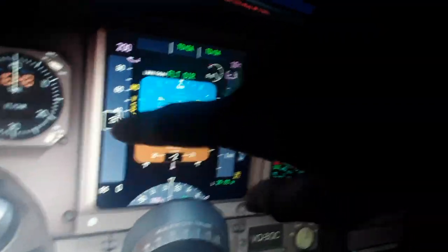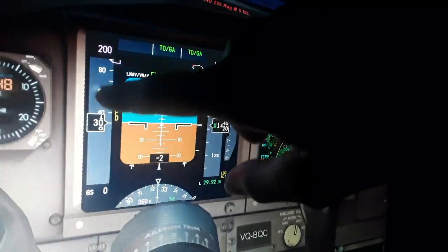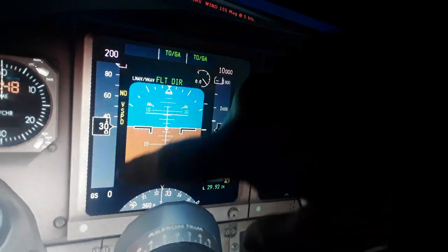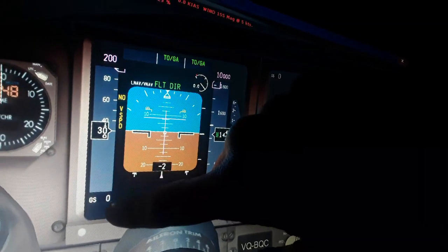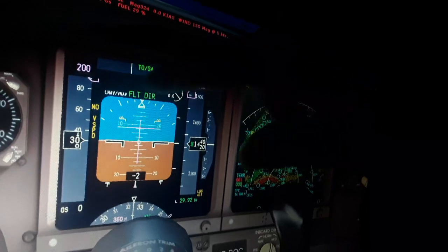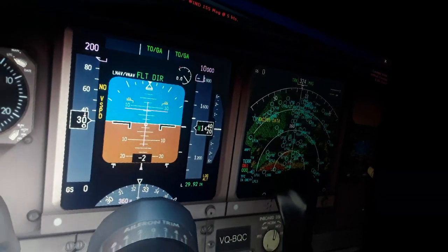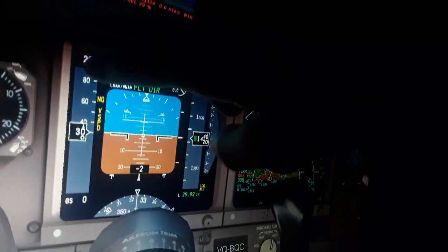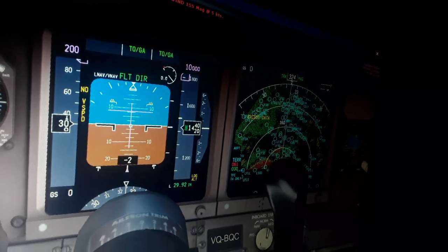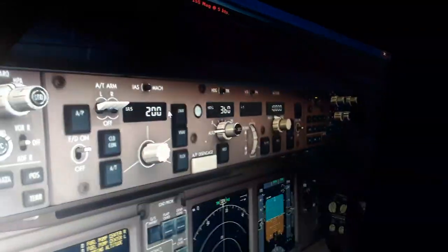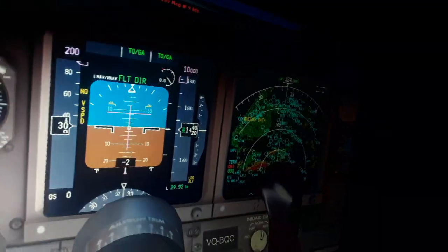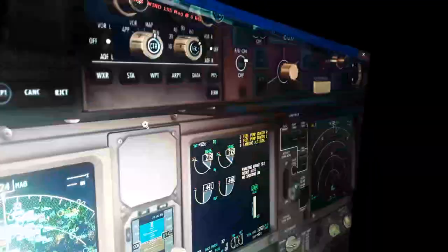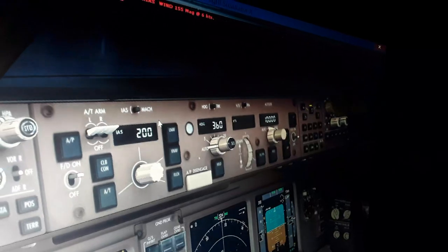That displays the airspeed tape. The minimum airspeed display right now is 30 knots. The actual airspeed is 0. The ground speed is 0. Because the aircraft is not moving, we have the airspeed selected from the autopilot. The target airspeed over here, 200 knots. We have the altitude here, the barometric altitude, target altitude, 10,000 feet over here.